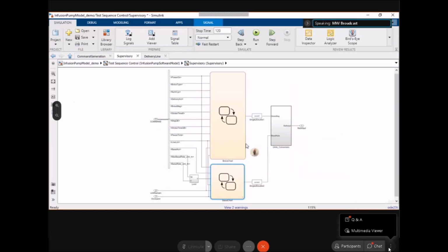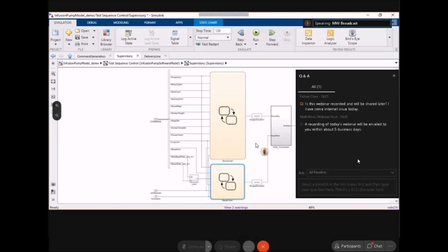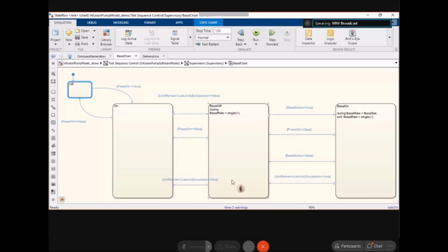Now, if we go inside the supervisory logic, you can see we have built this decision logic using a tool called Stateflow, and this is an add-on on top of Simulink, and much like Ed built that DC motor for you guys using drag and drop or quick insert methodologies, similarly, we can build a state machine. And if you go inside one of these state machines, you can see that it has multiple states. It has 4 states that it can run in, and it can transition between different states depending upon some conditions that are associated with those transitions.